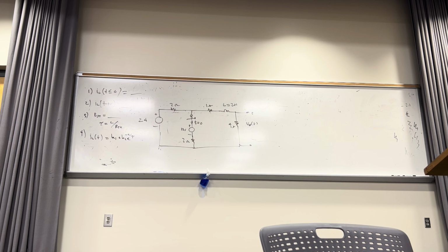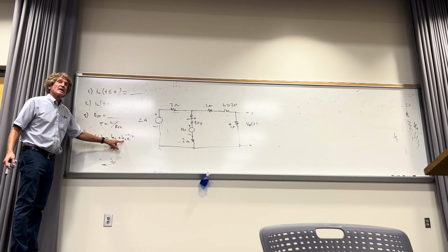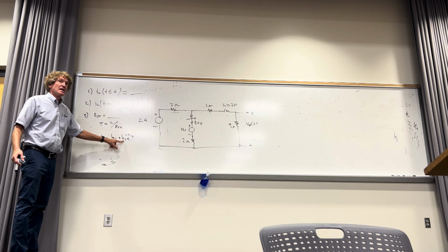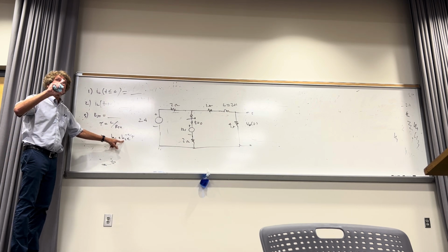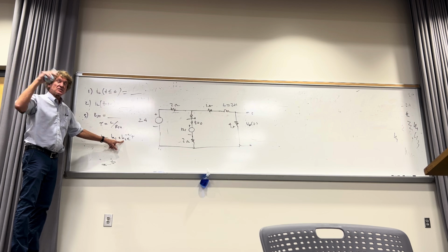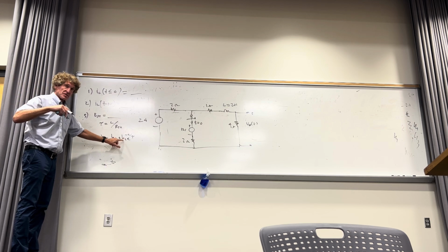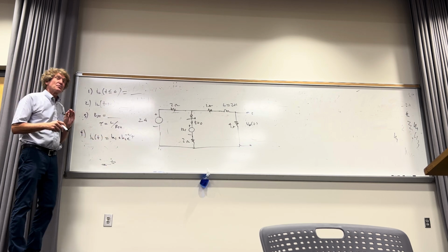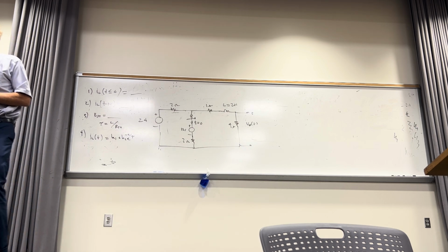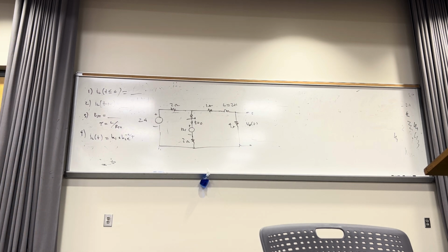The current at t equal infinity, right? Now K2, you don't know for sure. You may have to solve for that. If there's a current at infinity and a current just as a switch transitions from 0 minus to 0 plus, you're going to have to solve for this value. You all hear me, class? So you can't always assume it's the current for t less than 0. That is a common mistake. We clear on that? How many understand this? Now let's do the problem.